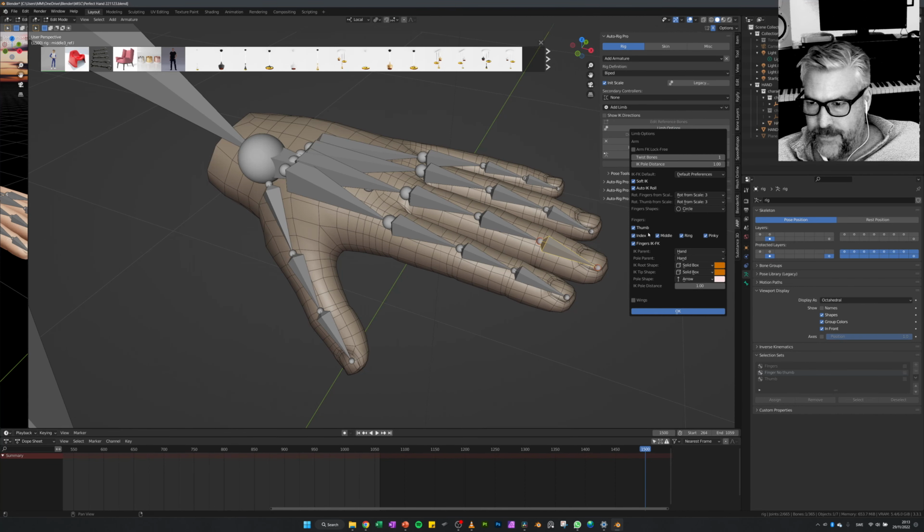I have chosen all fingers here: the thumb, index, middle, ring, and pinky finger. It's important to know that if you, for instance, have a cartoony character with only 4 fingers, then please make sure that you remove the index finger here and still use the pinky finger, since you have a very important control bone for the pinky finger.